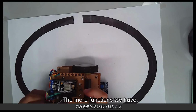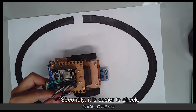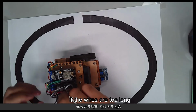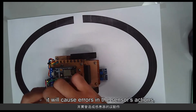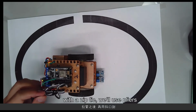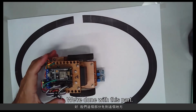The more functions we have, the wiring becomes more complicated, and organizing the wiring becomes an even more important task. Secondly, it is easier to check. We mainly do tasks such as avoiding obstacles or moving in a maze. If the wires are too long and accidentally get pulled off, it will cause errors in the sensor's actions, so you must pay attention to this. After tightening with a zip tie, we'll use pliers to cut off the excess. We're done with this part.